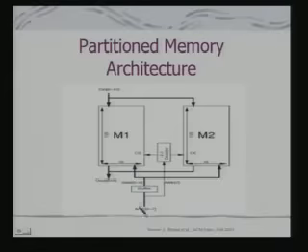Just look at this example, that this is a memory area which is using 0 to 7 address bits, that is you are having an 8-bit address bus, and this memory is divided into 2 blocks. So, the number of locations that are to be driven at a given point in time is 128, it is half of that of the complete block, and the other block would be deactivated because you are using a 2 by 1 decoder depending on the address bit 7, that is the most significant address bit.